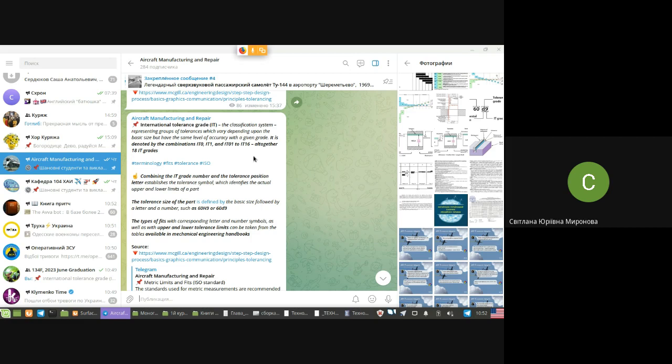So on one hand, in terms of assembling, this technique is great because during assembling you are spending less time and less money, and you don't need much preparation for assembly manufacturing because you have no need of jigs, if only some primitive jigs. But when it comes to manufacturing as a whole, including manufacturing of parts, of course it's inappropriate because you need to increase accuracy of parts, and any change in accuracy of parts significantly increases expenses for parts manufacturing.